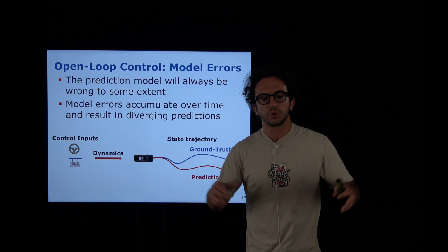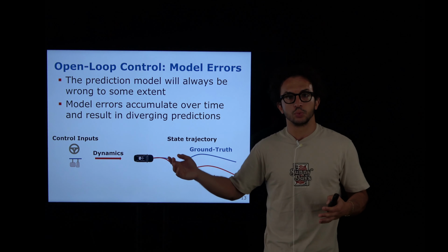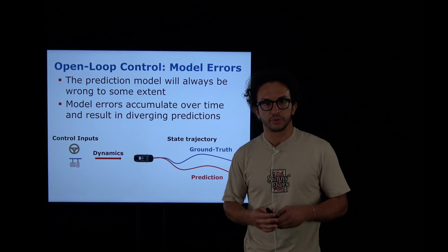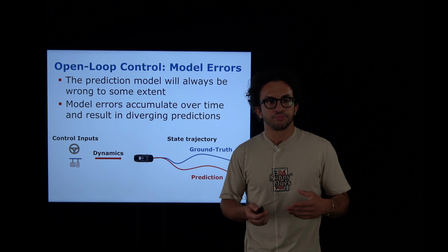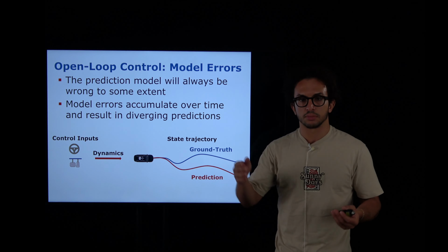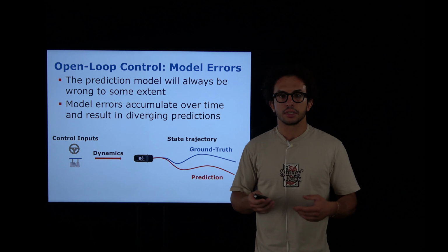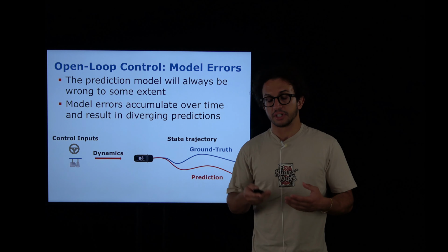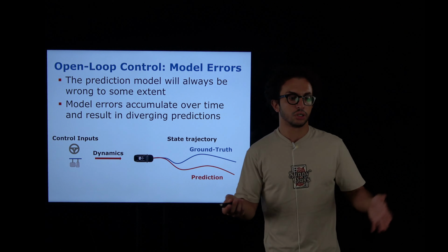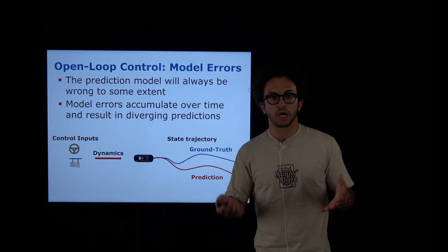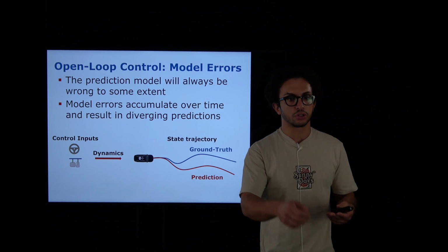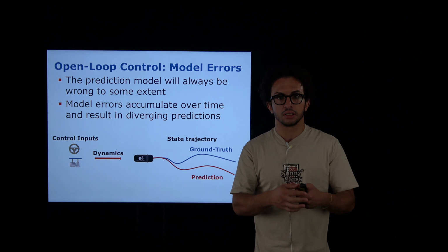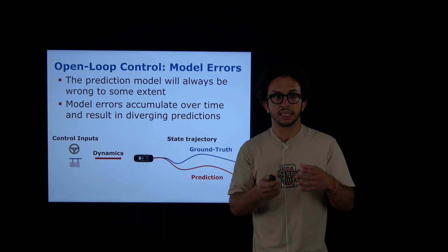What does it mean? It means that we have a certain model, for example, the dynamics that we've put in the constraints of the previous optimization problem, but that's not enough, because sometimes there are disturbances acting on the system, and so the dynamics is slightly modified, or there's some noise, for example, in the sensor reading, so the closed loop is a bit altered, or maybe there's noise in the actuator, so we compute a certain actuation signal that we have to feed the system with, but that's actually altered.